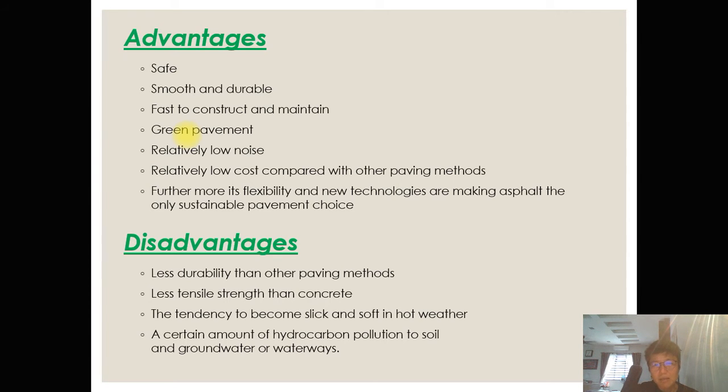However, bear in mind that those things that you scoop out are actually old and used. So when it's old and used, and you mix, say you use 60% of that because they're already broken, they lost their sharp edges for friction and all, and you add say 40% of the new stuff, it is definitely not going to be as good as in a situation where everything is new. Okay, so sometimes when we talk about using recycled stuff, you actually compromise a little on the quality. However, if the performance level is still within the stipulated standard, then why not?